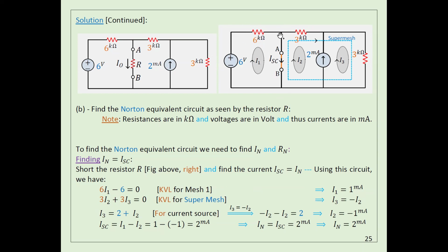Okay. I need to calculate the current here. The current here, we have I1. Here this current is going to split between this current and this current. So now I need to find the current here, on this resistance, right? Because if I already know this current, I need to calculate this current. So using Kirchhoff current law, I need to find the current here. Make sense? So we need to find the way to calculate the current on this resistance.